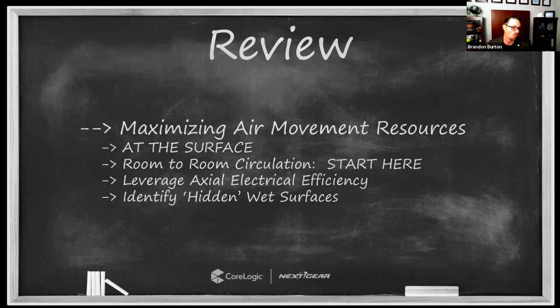With air movement, I want you to start heavy and lighten up as you go. Right? But the only way it works to start heavy is if you lighten up as you go. Don't follow the S500 recommendation or calculation for air movers to come up with 30 air movers in a property and then leave all 30 air movers there for 7 days. That's not practical. You do not need 30 air movers 7 days into a job. You probably needed them on day 1 if that's what the calculation said. But as you move through the process, you should be reducing the number of air movers. That is the right way to dry a structure.